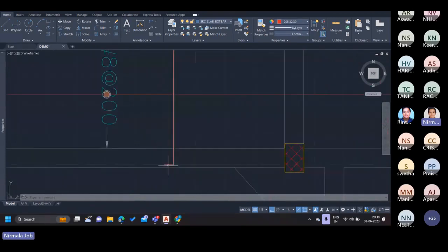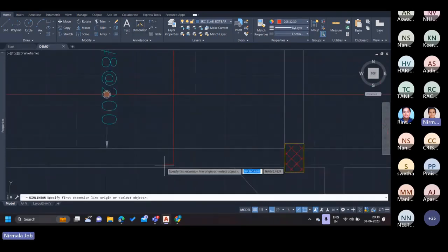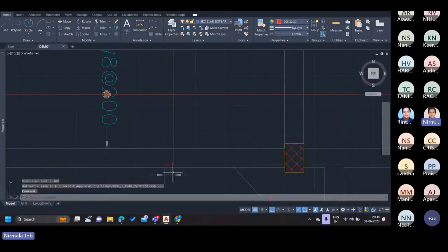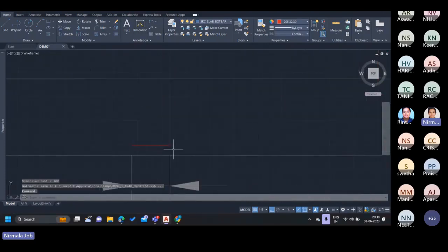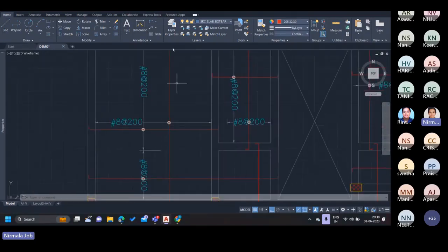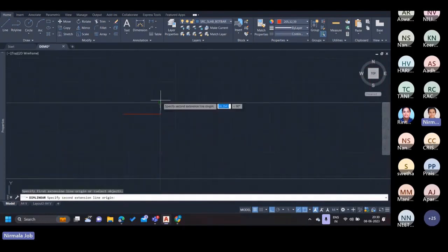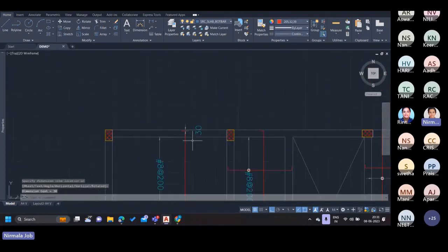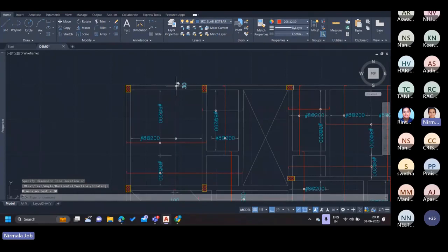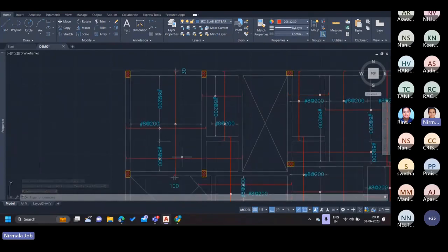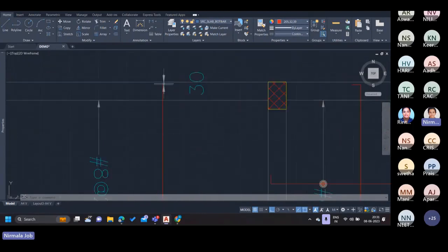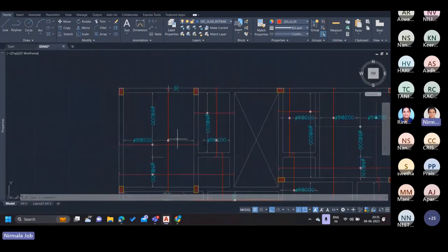And the bend is usually provided with a dimension of 100 mm. And the distance between these bars, and between these bars and the slab beam edges, is usually the cover itself, that is already discussed as 30. So we have to draw each bar and provide cover for each.